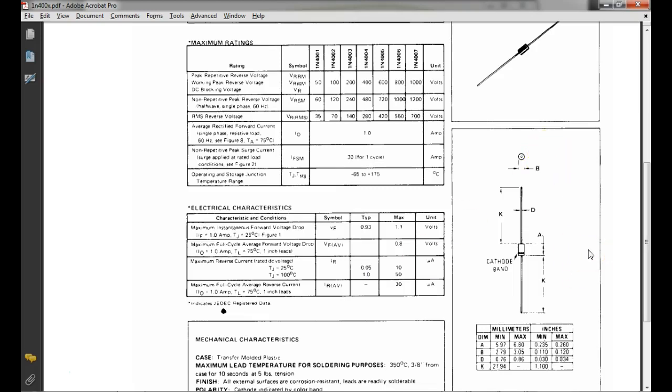So what we're doing is we're measuring the leakage current, right? How much it leaks through the solid state device when it's reverse biased. And that varies with, starts with T, temperature. That reverse leakage current varies with temperature. And we'll see this when we break over a diode. We're going to deliberately break over a diode, but we're going to put like a 10 mega ohm resistor in series with it so we won't destroy it.